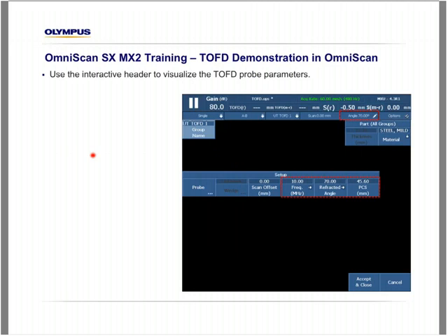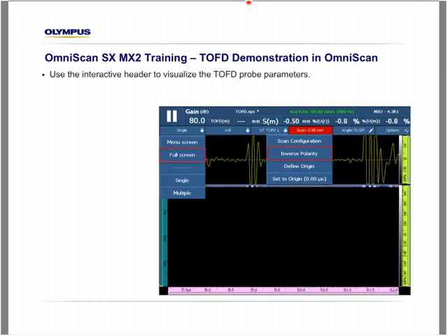After we have done the calibration, we can also right-click on the angle in the OmniScan interactive header and see our calculated PCS and the information of the probe and wedge from the wizard. Okay, this thickness, this PCS will become constants in the future inspections so that we don't have to use two targets in analysis mode. And I'll explain this more when we get to analysis.